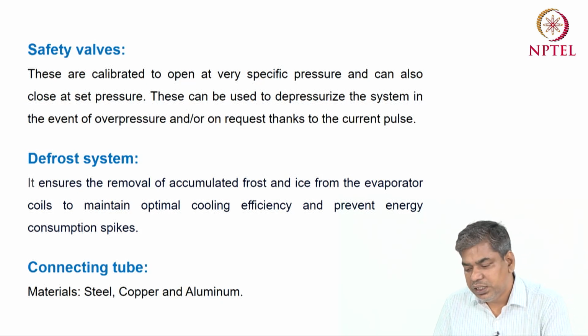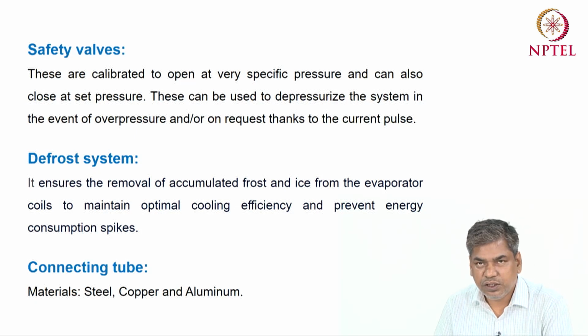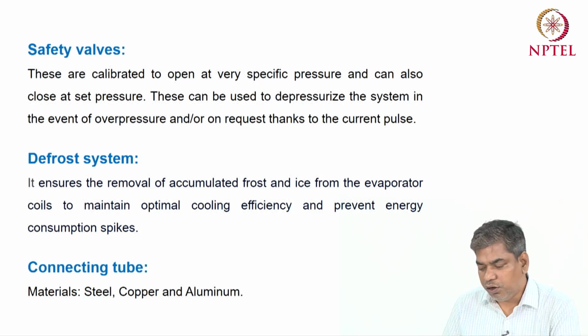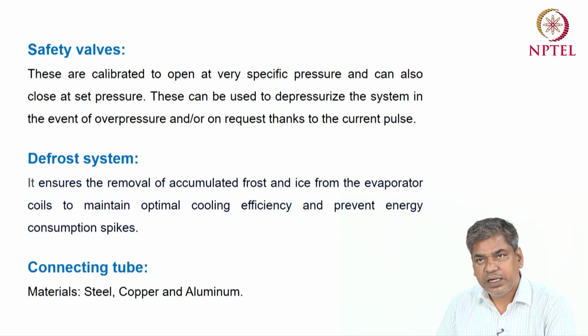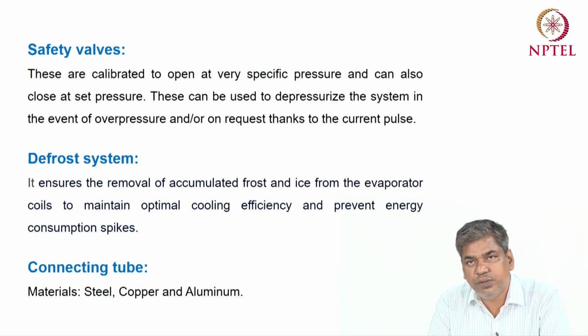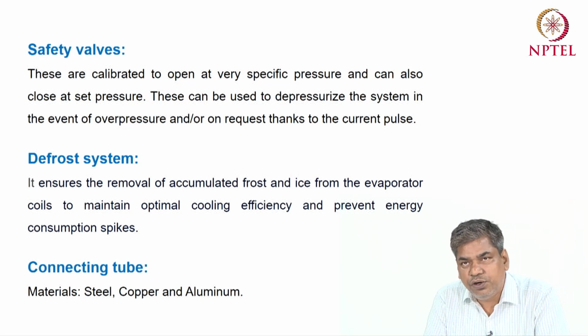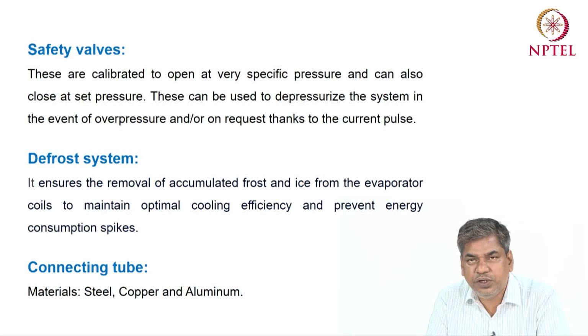So that's why, at a certain period, or periodically, we have to defrost the system. That means all the ice deposited on the evaporator, we have to remove. Okay, so that's why we have to use some defrost system for that application, and the different types of defrosting methods I have already discussed.